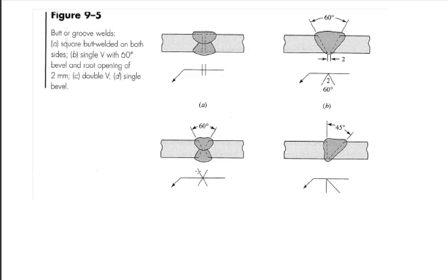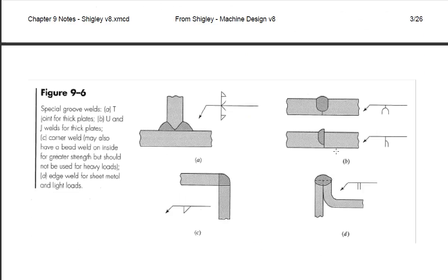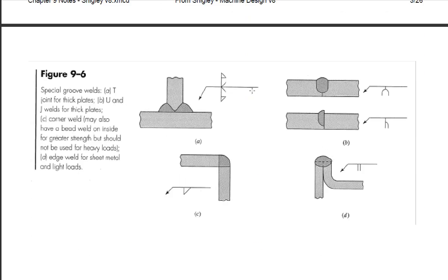This says cut a V on the weld side, cut a V on the other side. This says cut a bevel, or a 45-degree notch, on one side. This would say cut a 45-degree bevel and fill it with a fillet weld, and do the same thing on both sides. This would be a one-sided U-shaped notch, a one side on one plate only U-shaped notch.